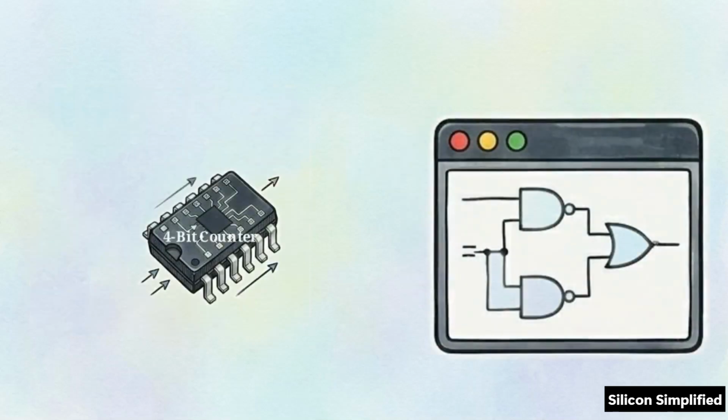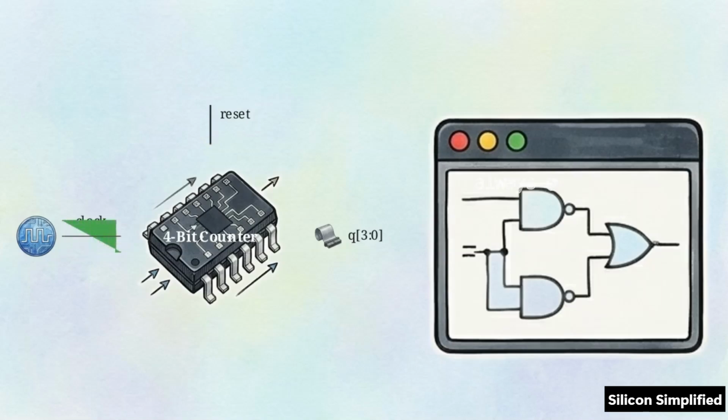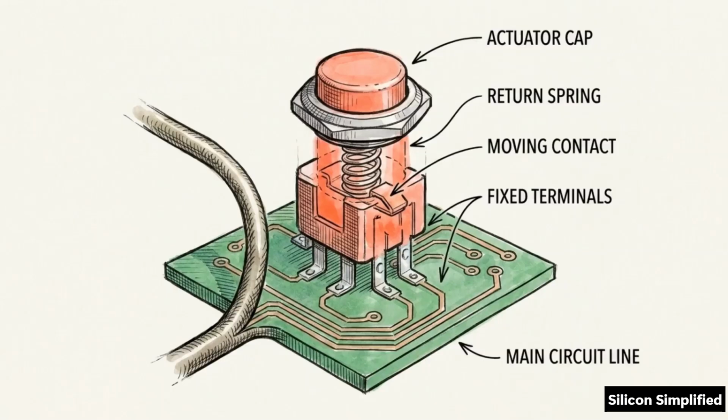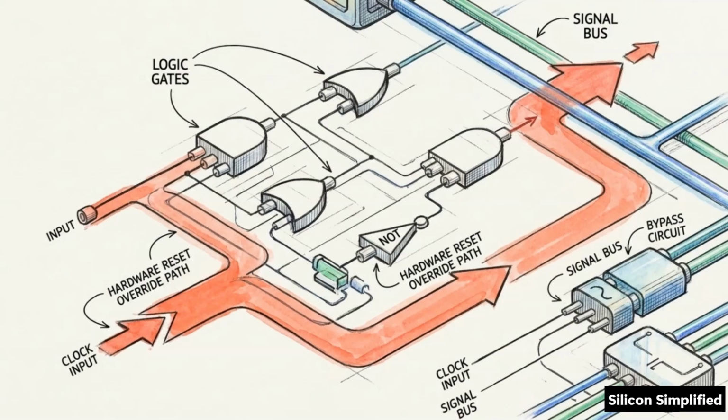This schematic shows our baseline architecture, a 4-bit counter with a synchronous reset capability. Physical hardware must evaluate its inputs simultaneously at specific recurring moments in time. The always block tied to the positive edge of the clock enforces that state changes only happen exactly when that rising edge occurs. Before the counter can count, it needs to know if it should be resetting. We have to prioritize the reset command over the standard increment operation.